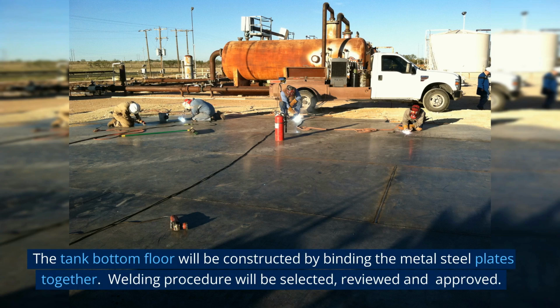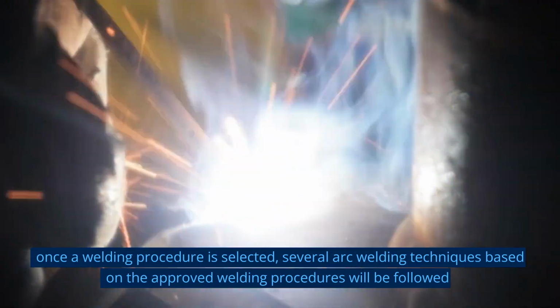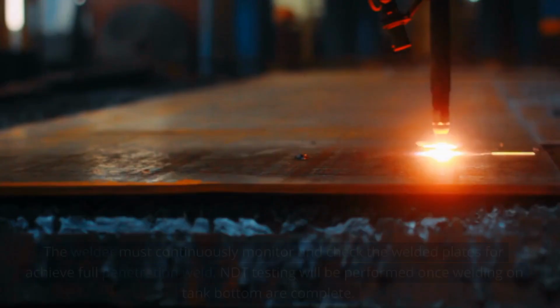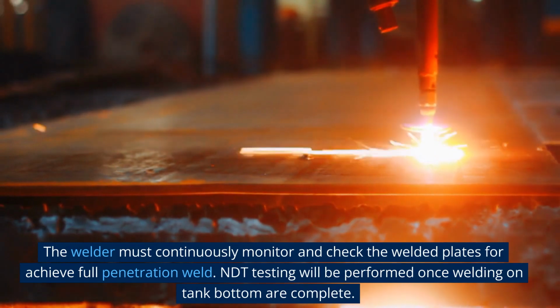The tank bottom floor will be constructed by joining the steel plates together. The welding procedure will be selected, reviewed and approved. Once a welding procedure is selected, several arc welding techniques based on the approved welding procedure will be followed. Metal sheets for the tank bottom can be butt welded with either square or V grooves. The welder must continuously monitor and check the welded plates to achieve a full penetration weld.